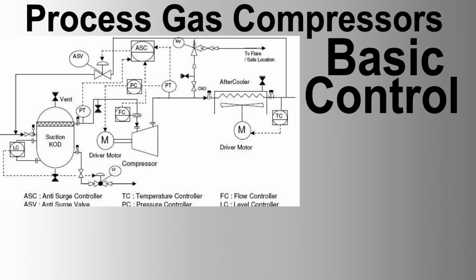C. Control integration. PID controllers use process measurements to adjust set points and control actions. Communication protocols use standardized protocols, e.g., Modbus, Profibus, for seamless integration and real-time data exchange between the VFD, DCS, and compressor control system.